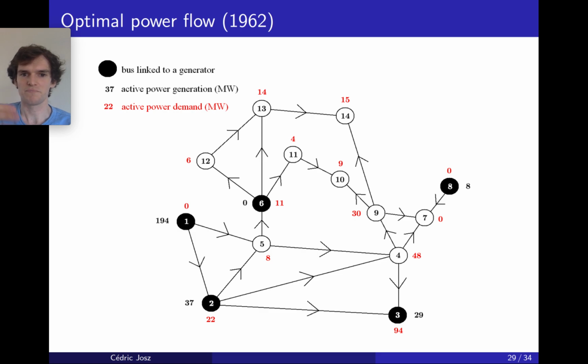So we have both fixed active power demand and reactive power demand, and then we have to compute the generation, both active and reactive. It turns out that this problem of computing how much to produce and all the flows, the arrows that you see, all comes down to just computing the voltages at each node. Each node has this notion of voltage, so here we have these 14 different voltages that we want to compute. Once we have the voltages, then we can compute everything else.